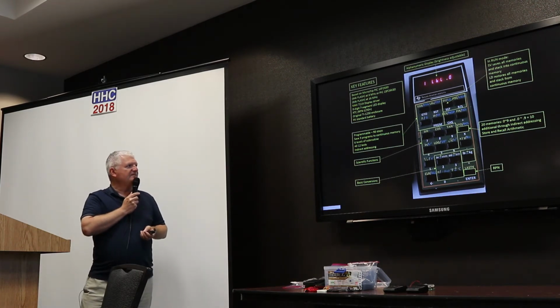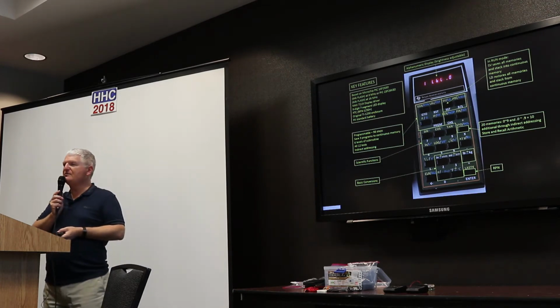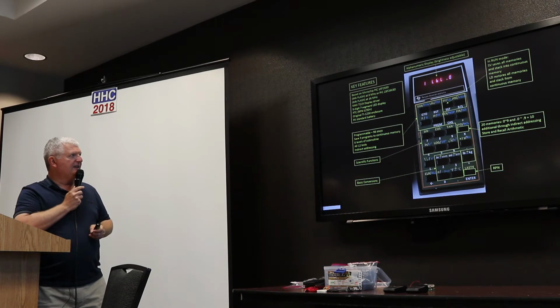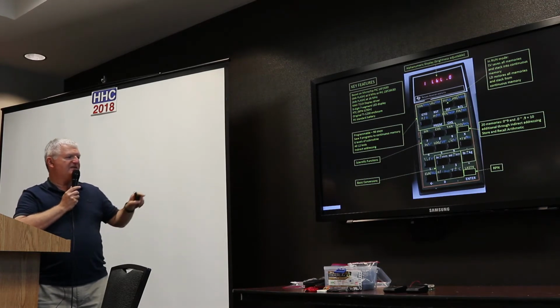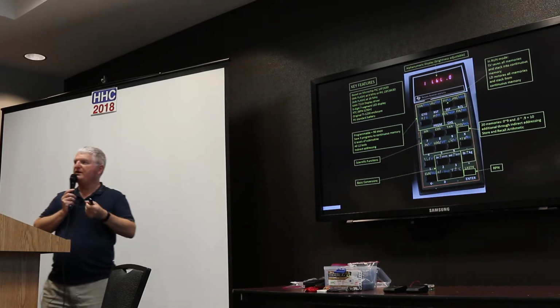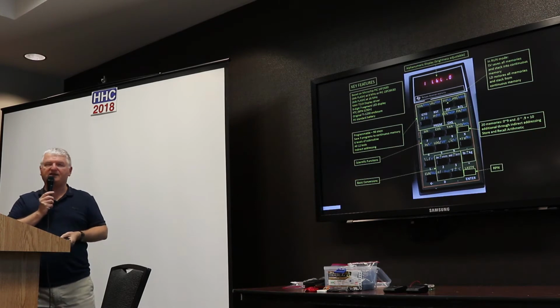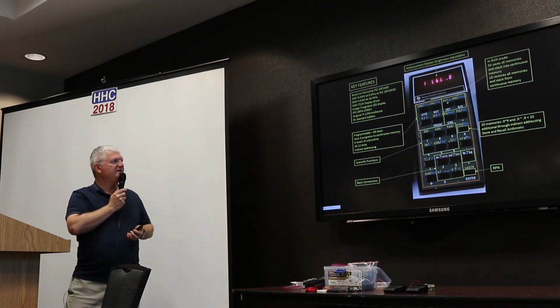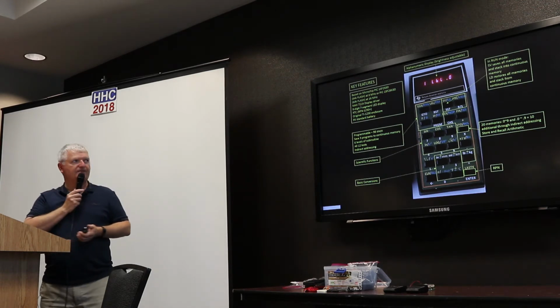The display is driven by a MAX7219 display driver. It drives 8 digits. For the 1250 Plus, I added a real-time clock with a battery, so you can get the time and date. The enclosure is the standard 1250, and it uses a 9-volt battery.